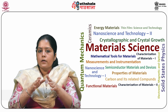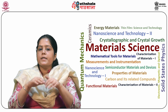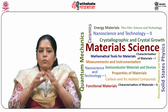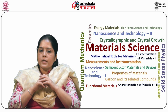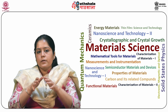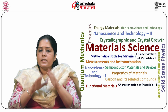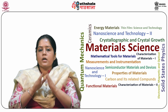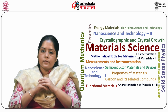Monolithic integration of individual cells is simple and is done by selective laser ablation, which allows for module voltage optimization. Silicon and hydrogen are abundant. The material can be doped p or n type with boron or phosphorus respectively. The material possesses the necessary electron and hole transport properties for PIN type solar cells.